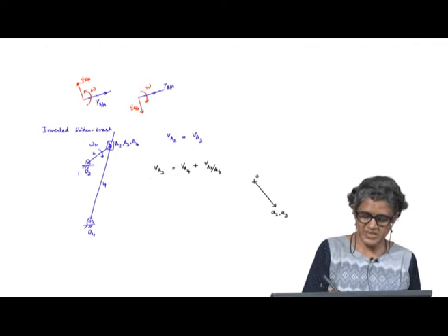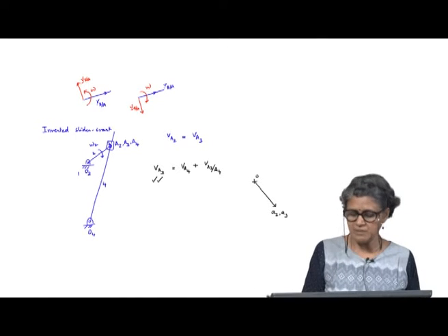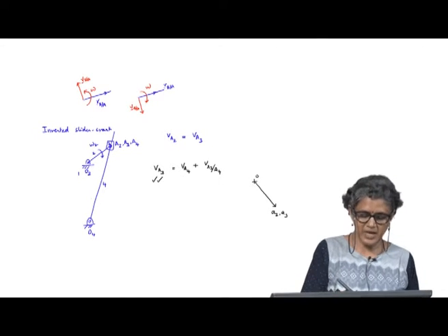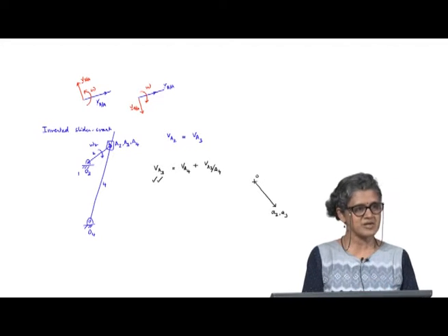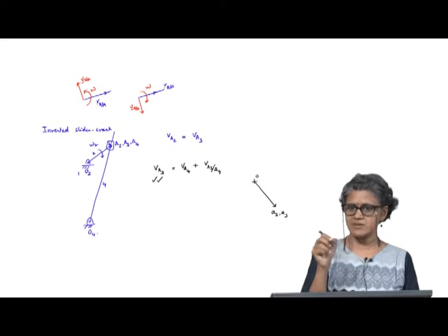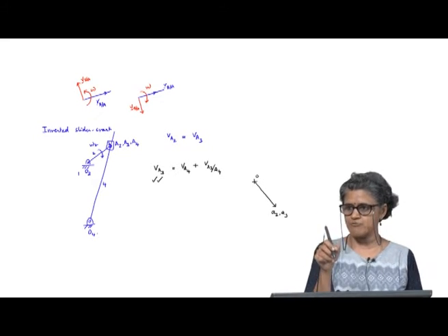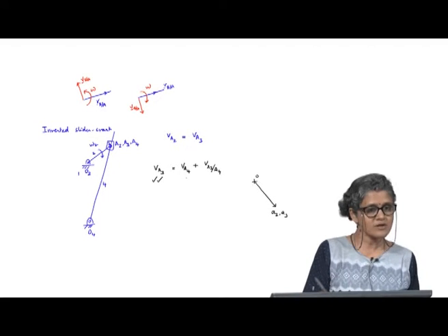Okay. So, in this I know completely the velocity of A on body 3, velocity of A on body 4. So, body 4, its absolute movement is pivoting about O4. Okay. So, if I take a point that is fixed to body 4, I know the direction of that velocity.